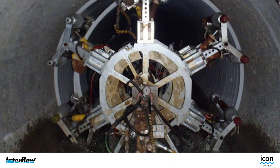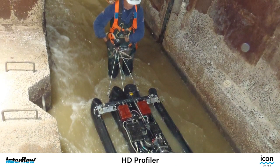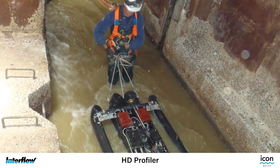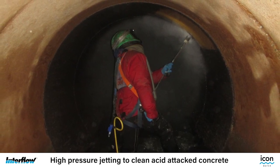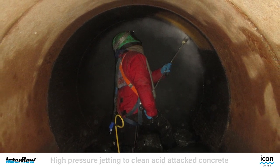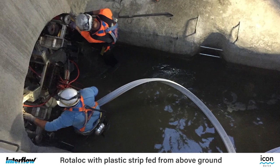in a high-flow environment. Other innovations included the use of HD profiling for detailed surveying to provide safer and faster information than traditional traversing. Cleaning methodology for the acid-attacked concrete surface to enable grouted liner to achieve a bond to meet stringent design strength requirements. Revolutionising the handling of a plastic profile strip in the high-flow conditions.